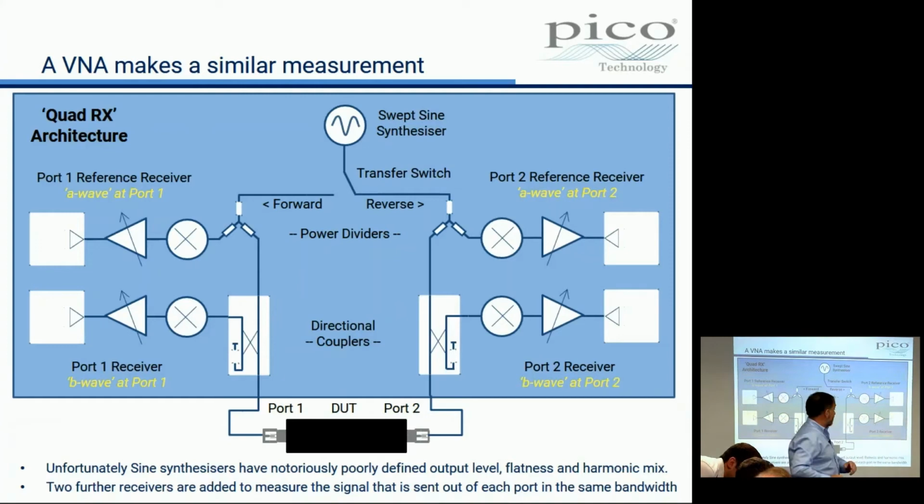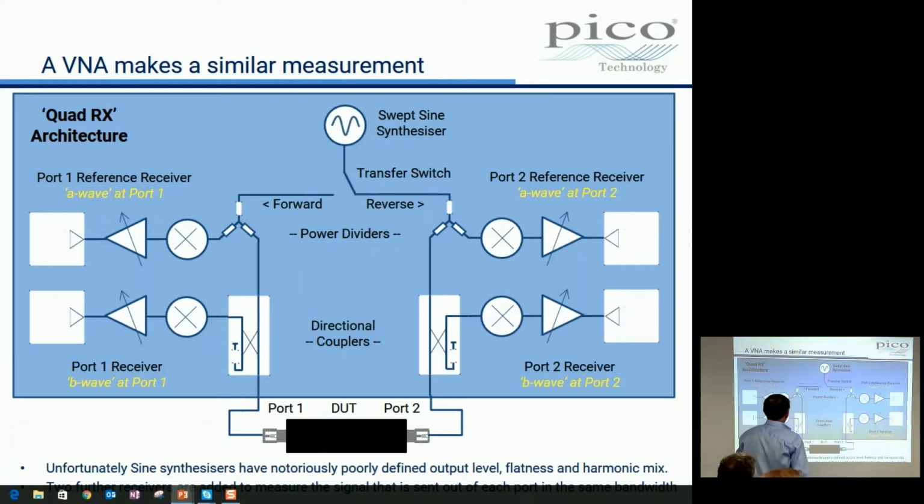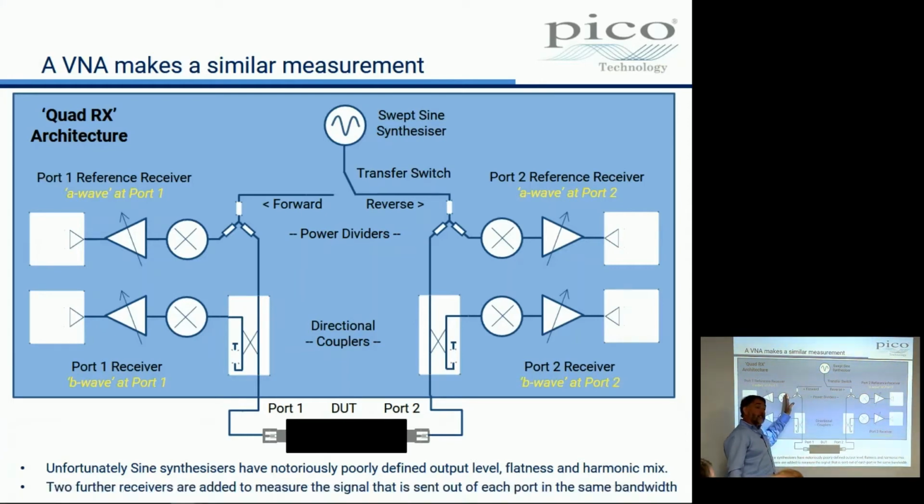Now, a 1 megahertz signal we can put into a 100 megasample per second A to D, a scope. So that's essentially what we've got here, a 4-channel scope with mixers on the inputs. Now we could have mixed all the way down to DC, with a 3 gig tone into the mixer.